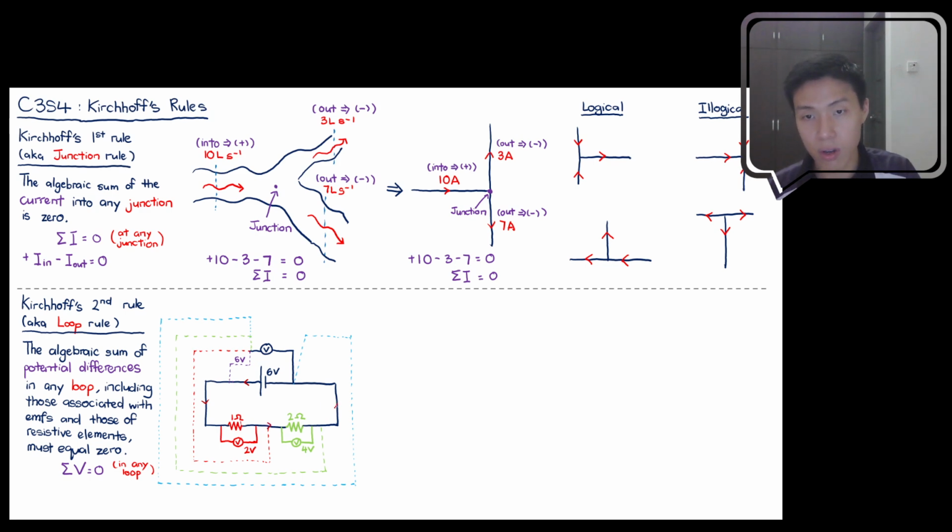So I'm following this direction of current, shifting my voltmeter leg down the current path until I get past the 1 ohm resistor. Now I'm referring to this red leg. The right leg is still fixed at this point, but my left leg is shifted to this point over here.